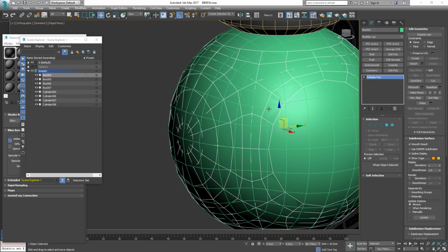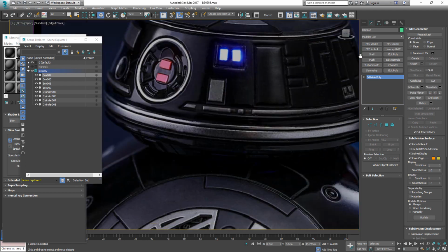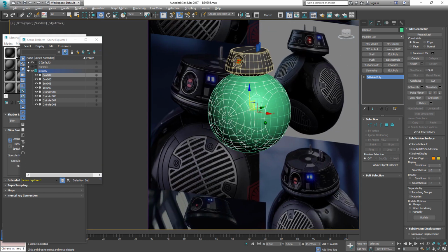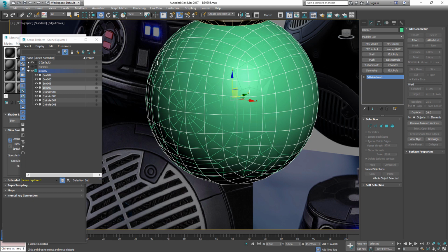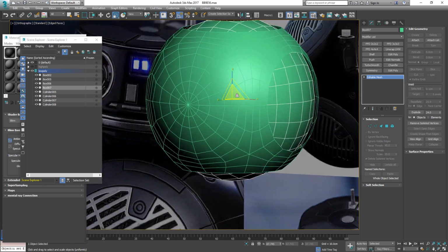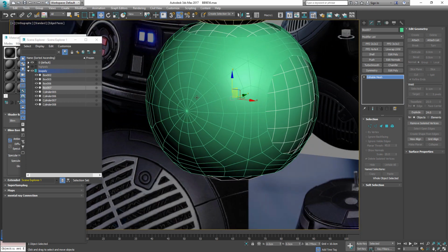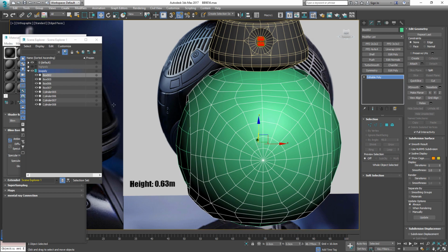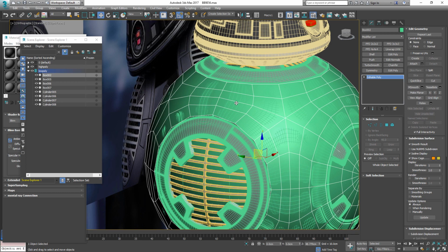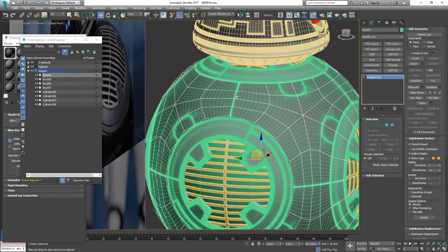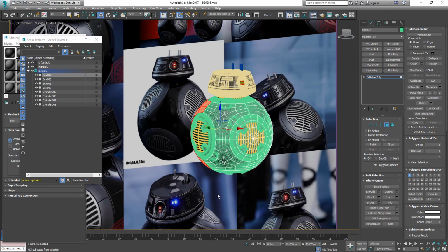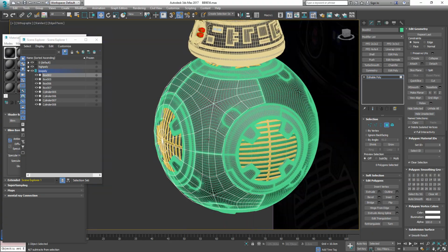So that sphere that we just created here for reference to match these 2, we can reuse it for this kind of an extra sphere that's there in the inside. So let's take it, go over to scale mode, and we just want to scale it down a little bit. So now it's time to already think about our unwrap, and for that I'm going to select our outer sphere again on the low poly. I'm going to show the high poly here for a moment, go in transparency mode, and we want to basically delete the other half of it here. Just select it and delete.